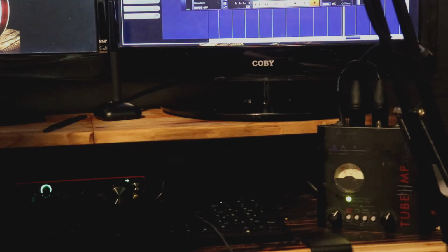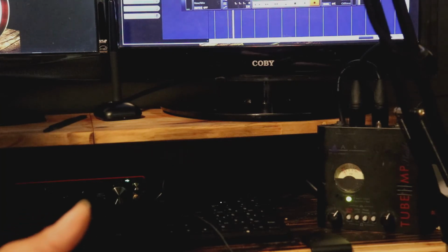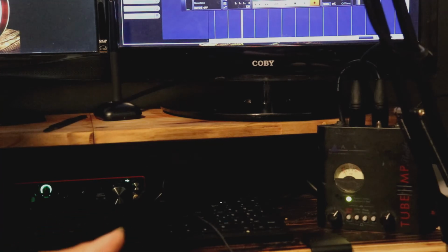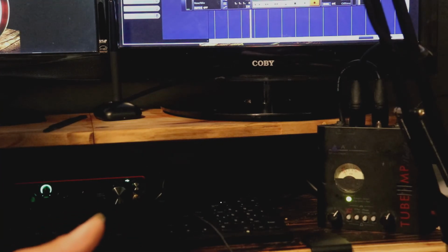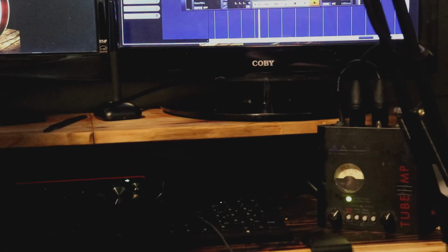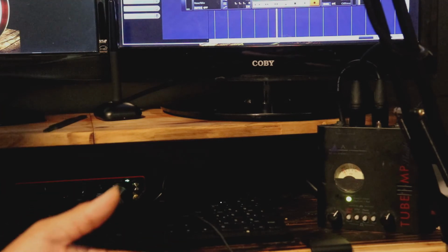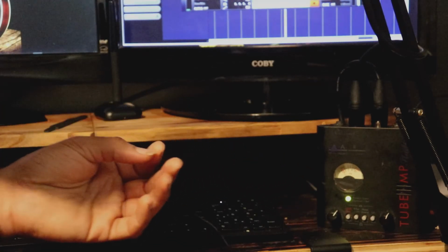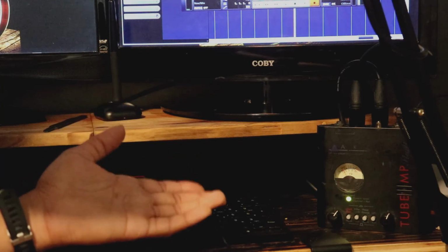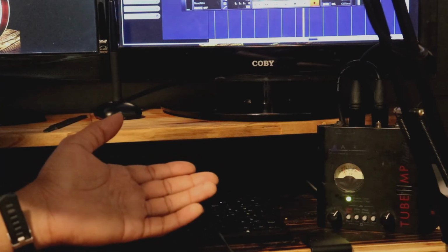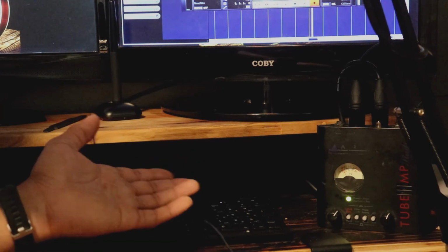The only other complexity with that is that if I'm going to go as far as to make a tube amp, then I'm going to have to wire it at 120 volts input and use a transformer and operate it around 120 to 200 volts. If I'm going to do that, I might as well just make a whole new microphone preamp unit instead of just making an active tube EQ.